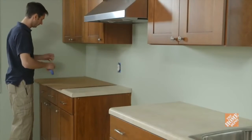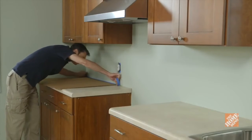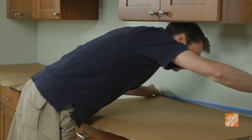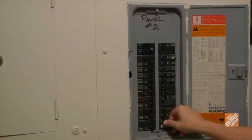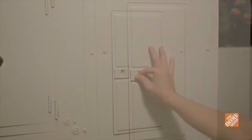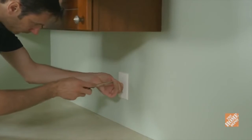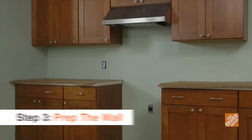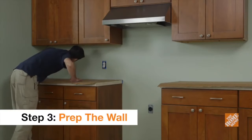Place a layer of cardboard or heavy-duty craft paper over your countertop to protect it from debris. Tape off the existing countertop as well as the underside of the cabinets to protect those surfaces. Also, shut off the power to the electrical outlets or light switches in your work area. And remove any faceplates.